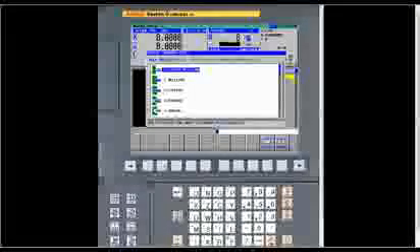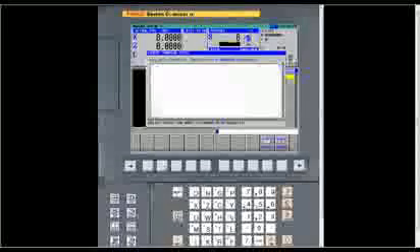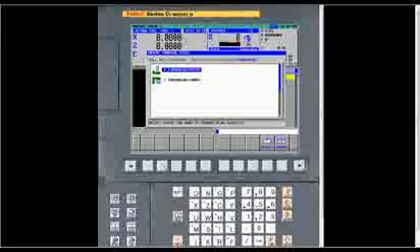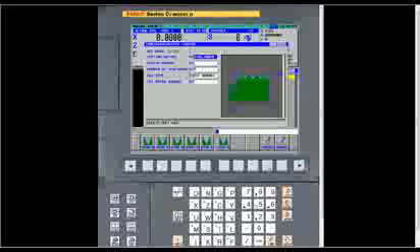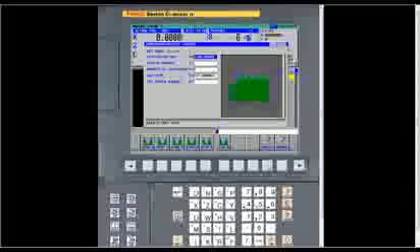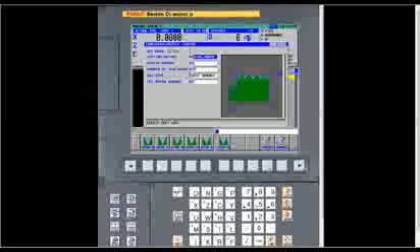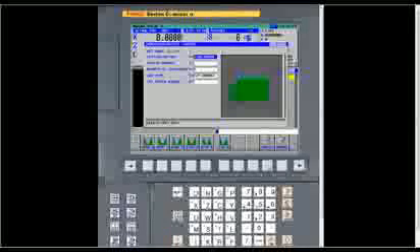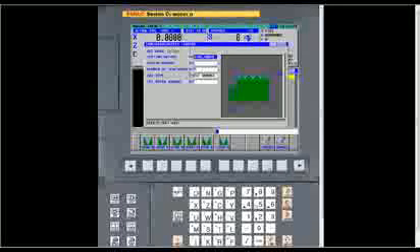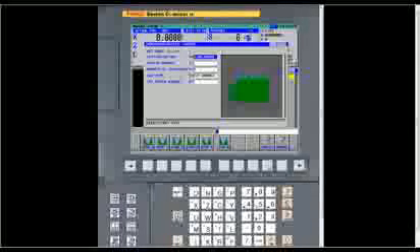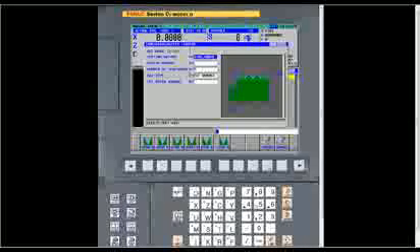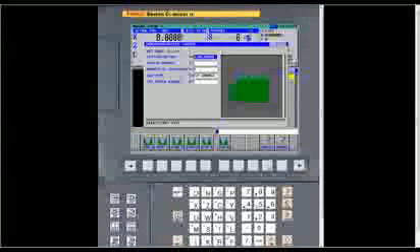And we go back, we've done our grooving, now threading. Again, threading is very simple. Fill in the blanks again. We select threading, outer. The cutting method, that's just how it is feeding the tool into the thread itself. And it defaults to single amount. And what that is, that's like on an engine lathe when you've got your compound set up on 30 degrees. And as you go in deeper into the thread, it's only cutting on the leading edge of the insert. That's what it defaults to.